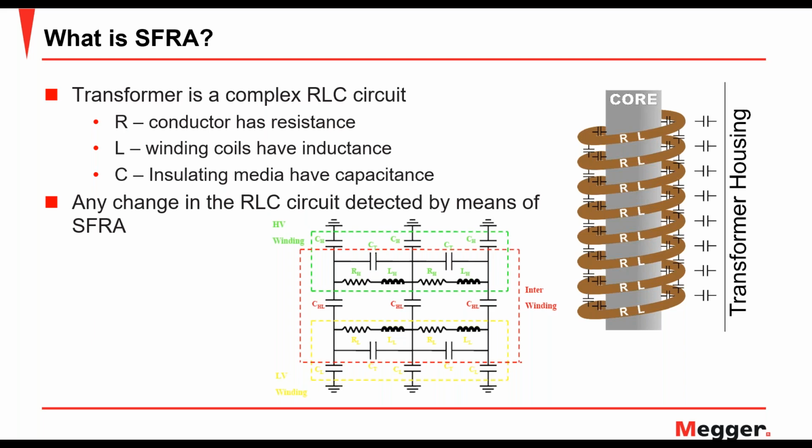The windings operate at different voltages. They need to be isolated from each other. And how is that done? The windings have paper insulation on them, and then there are barriers between windings. There are wooden blocks for support. It's typically filled with mineral oil. Other liquids could also be used, but typically what you see is essentially paper and oil insulation inside the transformer to insulate the windings from each other and to insulate the windings from the ground, which is the tank.